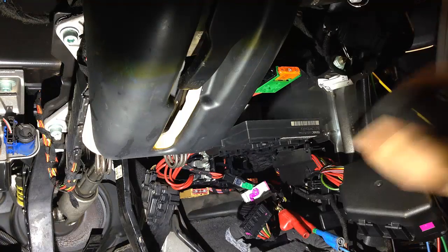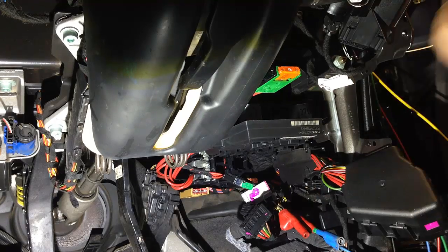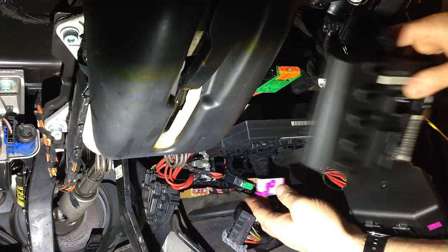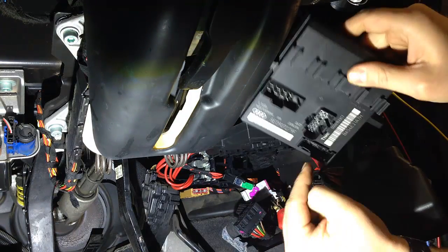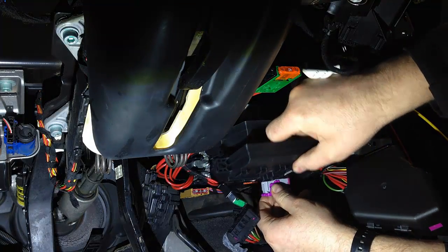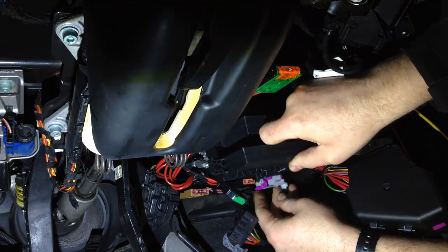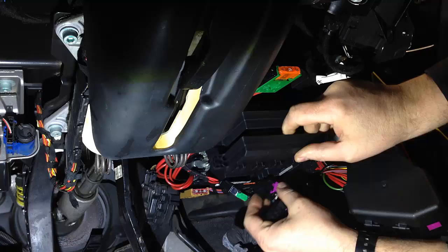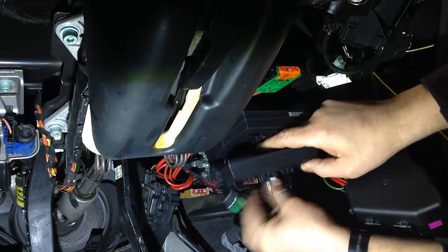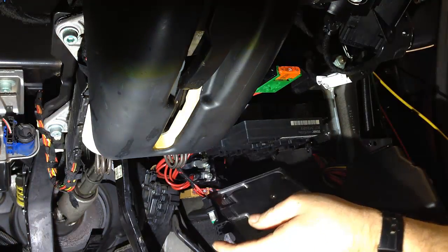I've got the other unit unplugged from the test that we were doing yesterday. Still got the scope leads hooked up. So it's a case of ignition's off, system's asleep. We're going to line the connections up. There are 3 connections we're going to make to connect this one back up to the car. The casing's made of plastic and there is no ground point, so it's using an external earth, so we don't actually need to fit it up to the car to get it to function. We can just rest it there. So we'll put the 3 connectors in. There, the 3 connectors are now in.